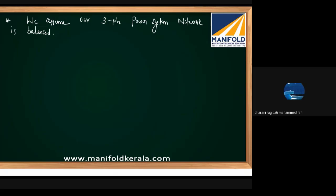We can carry out the analysis between one phase and neutral. Okay, so neutral only exists in which system? Star connected system or delta connected system? Neutral only exists in a star connected system. So that's why we always assume our power system network is star connected and we do our analysis.